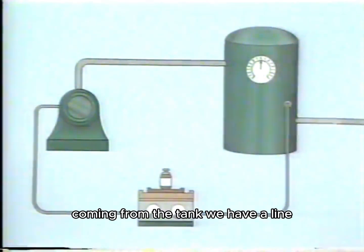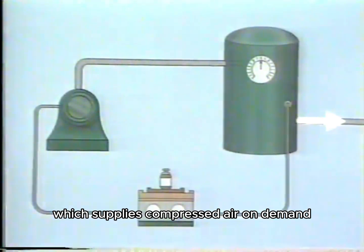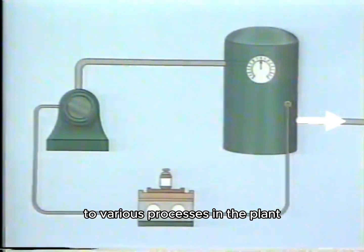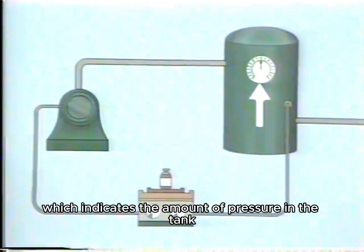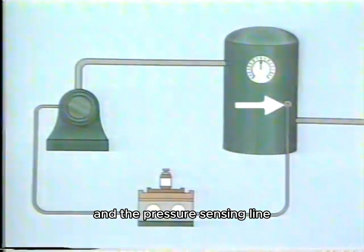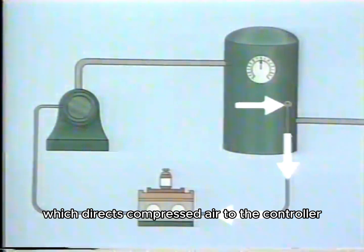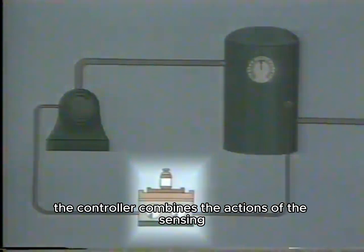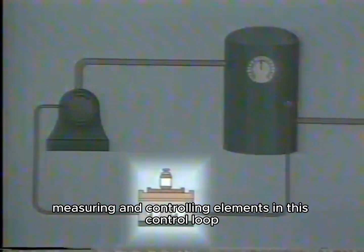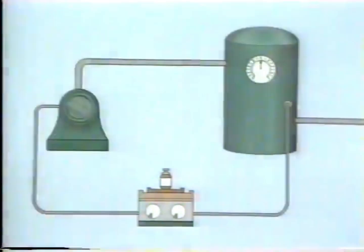Coming from the tank, we have a line which supplies compressed air on demand to various processes in the plant. The pressure gauge indicates the amount of pressure in the tank, and the pressure sensing line directs compressed air to the controller. The controller combines the actions of the sensing, measuring, and controlling elements in this control loop.